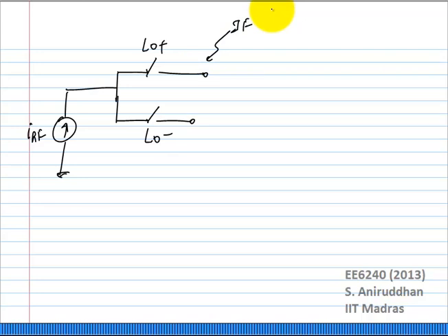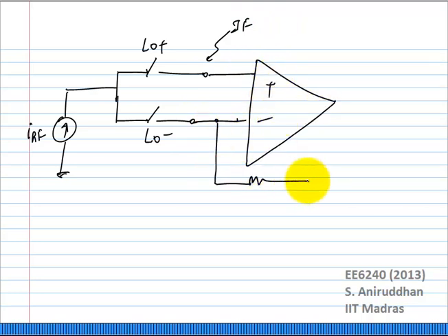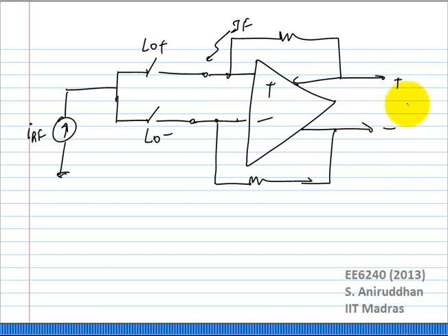Okay, this is the IF port which may even be baseband. Let's take the case of a direct conversion receiver. That's the simplest case, right? Inductor. No. Why would you want to use inductors here? So the easiest way to actually sense this and get a zero impedance is to take the output through a transimpedance amplifier, which gives you a virtual node at its input.